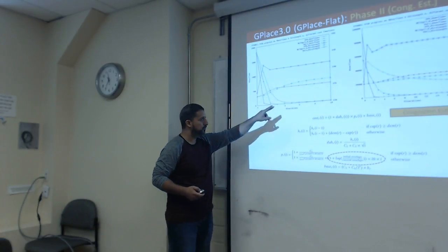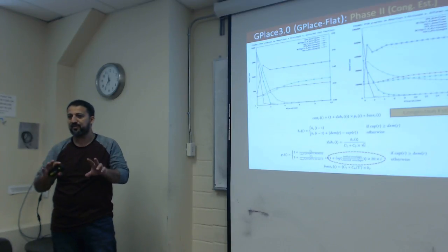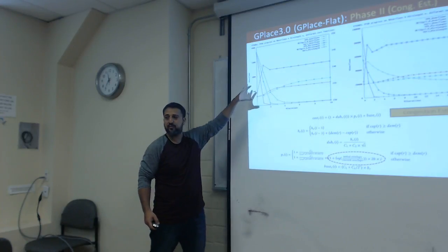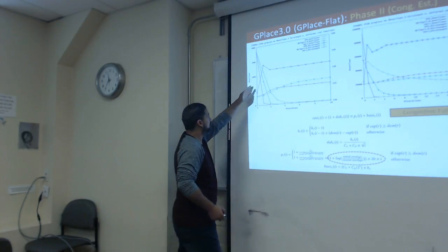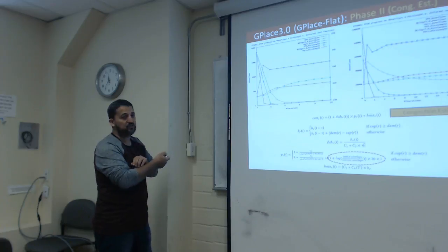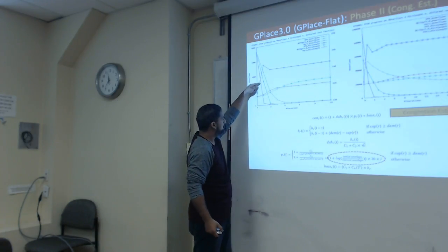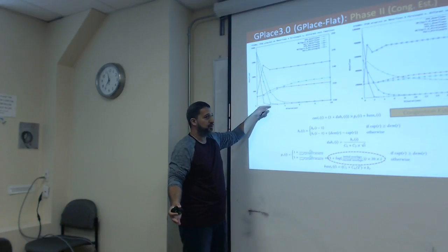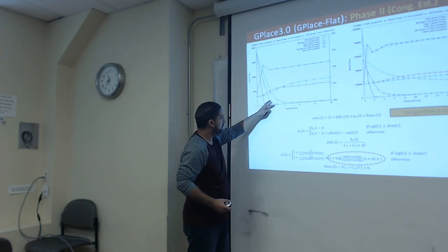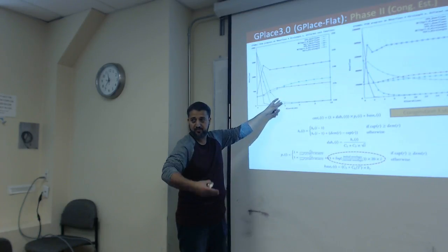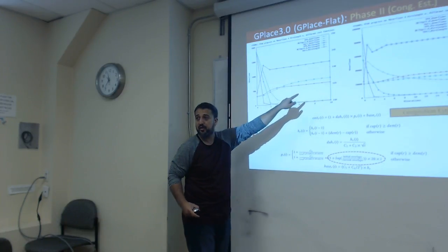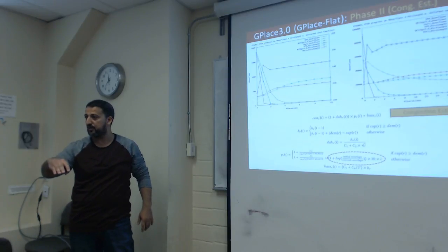We found that this is two benchmarks, but the behavior is similar for the 12 synthetic benchmarks. If we look at FPGA 1, for example, it shows two things: the overflows as well as the wire length. These three curves show the overflows for the cost function if we use the same one as PBR, the cost function used for ASIC, and ours. We found that the PBR cost function quickly gets rid of the overflows, but it has overshooting in the wire length. For ours, we get rid of the overflows quicker than the ASIC cost function by adding the adaptive present cost. Here, the brown is our wire length. So we get rid of the overflows quickly, and we also end up with better wire length at the end.